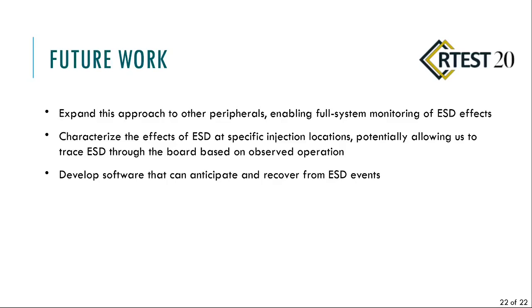Future work from here, we would like to expand this approach to other peripherals so we can monitor the entire system for ESD effects. We'd like to characterize the effects of ESD at specific injection locations, so that if we shock the board at a particular place, we see a particular kind of error or behavior, and we can better identify what's happening on the hardware based on what we can see with the software. And we'd like to be able to develop software that anticipates and recovers from these ESD events, perhaps by rolling back to a known good state, or in the worst case, resetting some of the hardware so that it can recover.